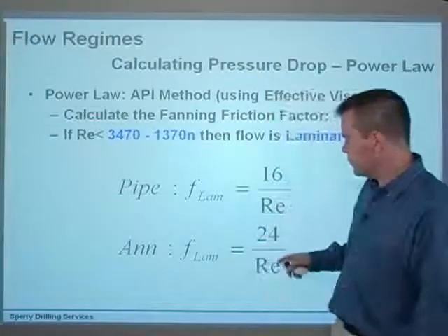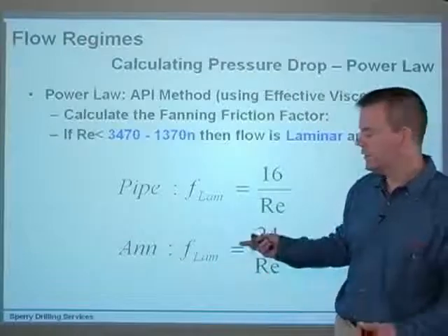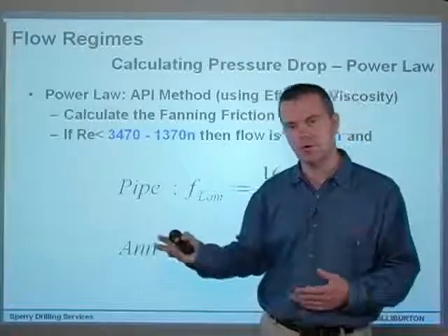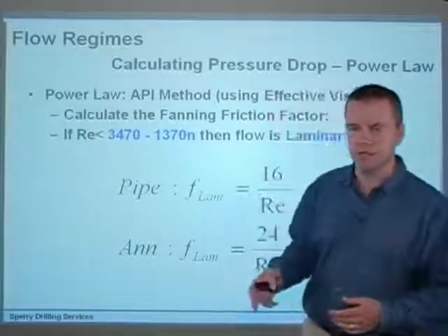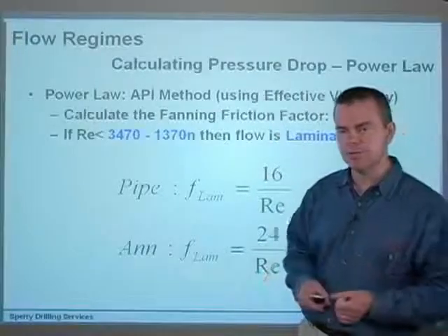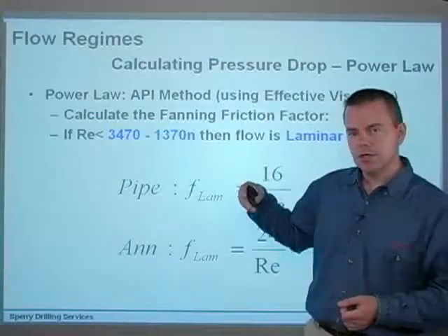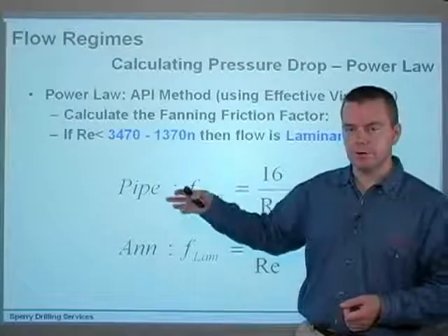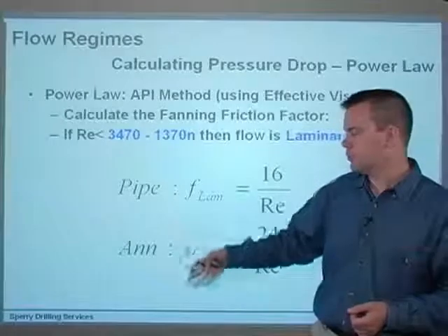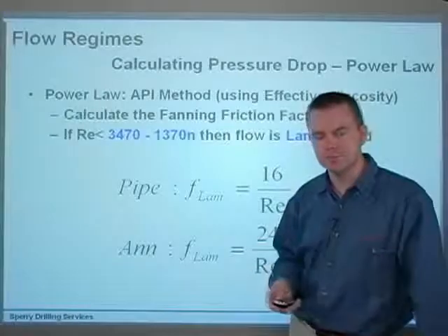Generally it will be laminar in the annulus, and almost certainly turbulent within the pipe at normal drilling flow rates. Not always, but that's a fairly decent generalization. You have to use a turbulent friction factor, or certainly an intermediate one, for inside the pipe, and in the annulus it will generally be laminar, perhaps intermediate.